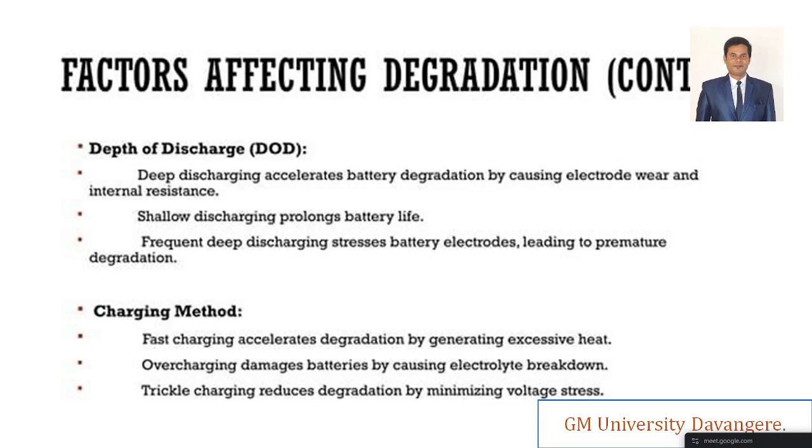If the battery is charged to 70%, and 100% comes down to 70%, then what are people doing? Again they go for the remaining 30% and compensate to 100%. That will not give prolonged battery life. Obviously it will cause degradation, the premature degradation. Somewhere the electrodes may have variable stress on them, right? So the electrode will have a lot of stress.